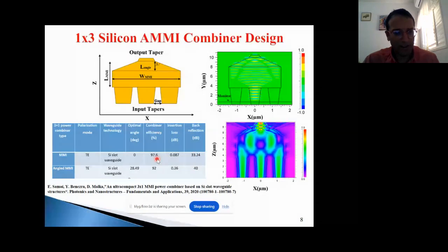but of course there is a penalty. If the intensity here was 87%, we reduce it to 82. There is always a penalty in engineering. You can improve one item and you will lose another item, but here it's very crucial, because back reflection is the most critical aspect in a communication system and in data center transceiver rooms, because if not, it will not function well.